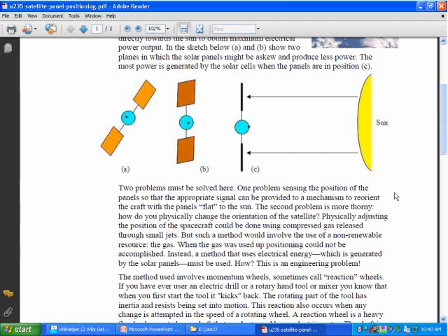Actually, a little bit of an aside that isn't mentioned there, they do have a 4th one that comes out at an oblique angle, and that's a backup on all the others. You wouldn't want to have 6 of these out there because weight in a spacecraft is a big consideration and power as well. But by having one come out at an oblique angle and doing some pretty complex programming, you can have it take over for any one of the others failing, and perhaps even 2 of the others failing. You could achieve some element of control with more complex programming. Well, the programming is fine because that's just little bits being stored someplace. Even though it's complex, it's possible to do it.